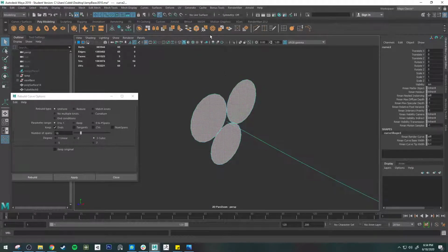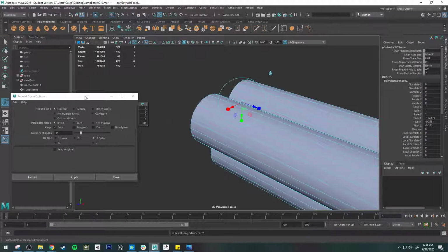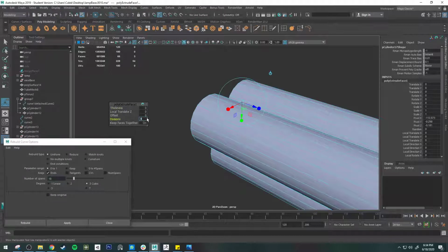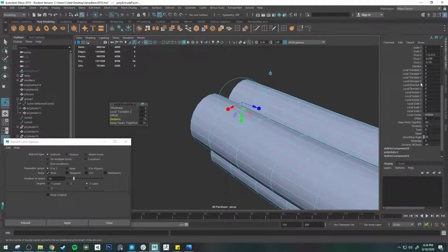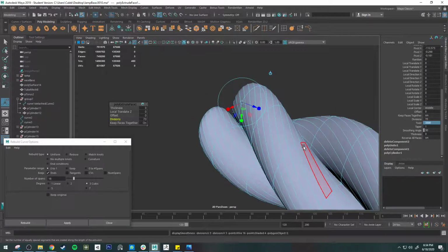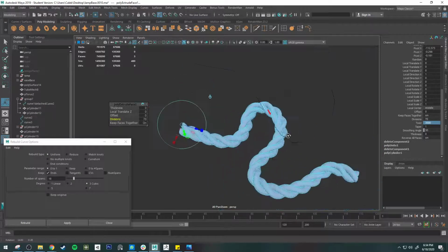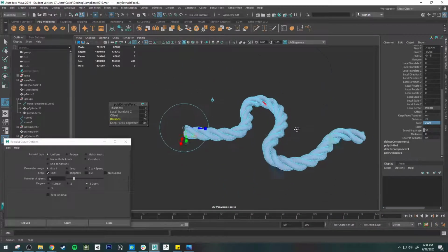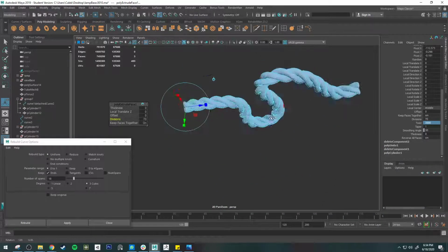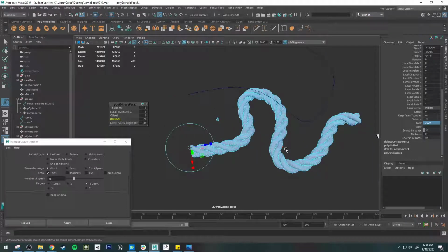So we'll take this, extrude, divisions, 70, twist, 3,000, smooth my object out, and it's a little less noticeable. I still feel like I'm getting it down at the end, so I probably would want to start tweaking that a little bit better. And then the other thing I could do is, oh, actually, what I was going to say was,